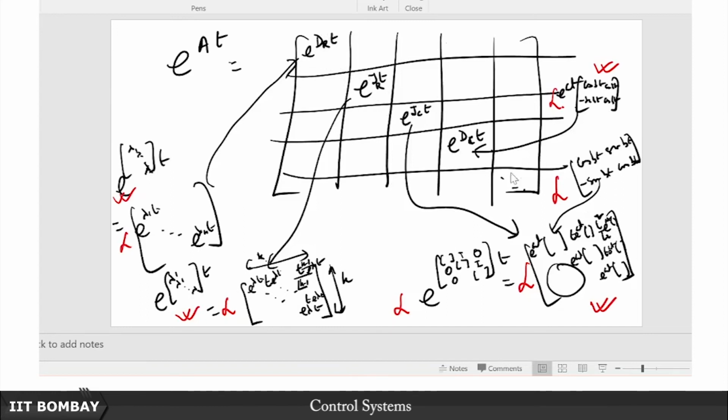So no matter what the degrees of these other blocks are, the overall degree of this denominator polynomial cannot be equal to n. If this A is of size n cross n, then already this part is yielding a denominator polynomial of degree k minus 1. So this part can at most yield a degree equal to its size, this part can also yield equal to its size. So you are already deficient by 1 here. So you've seen that one part of this loss of controllability and observability, that is either of those gammas or betas being equal to 0, translates beautifully into lack of minimality.